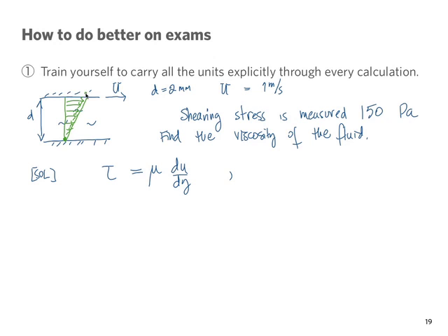Remember, there's a no-slip condition, so the fluid sticks at the wall. So if the wall at the bottom has 0 velocity, the first layer of fluid has 0 velocity. The top wall is moving at velocity u, so the layer right next to it is moving at the same velocity, u. So the fluid in between has to adjust from 0 to capital U.